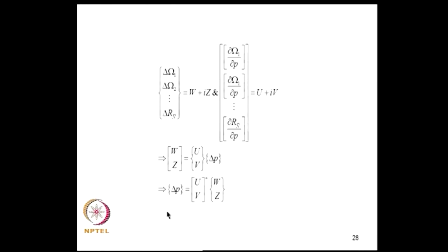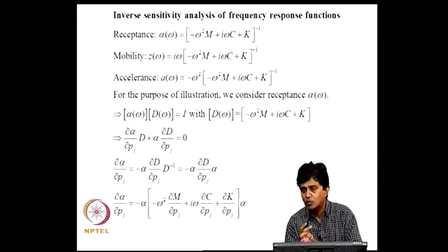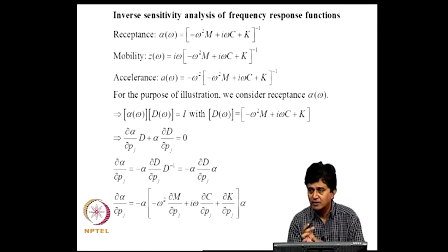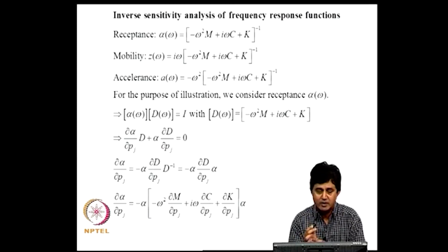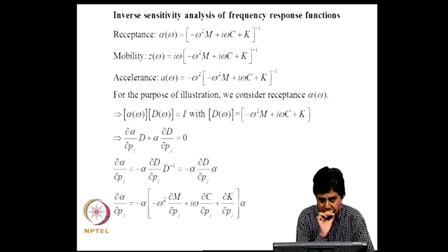Since they are complex valued, to facilitate computation I can separate real and imaginary parts, rewrite the equations, and I get the final updating equation to be this. This is with respect to natural frequencies and mode shapes, which could be real valued or complex valued, and you can include as many modes, as many orthogonality relations as you wish, and develop these methods. Now if you look into the experimental modal analysis literature, the primary quantity that we measure in an experimental work often happens to be either the impulse response function or the frequency response function.